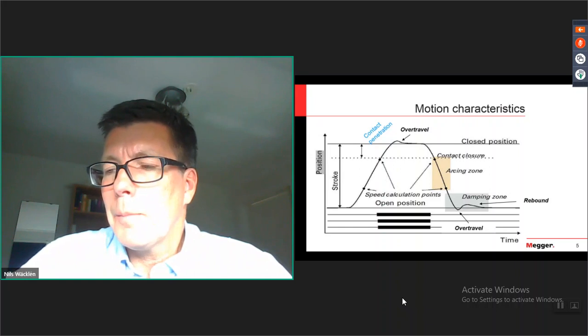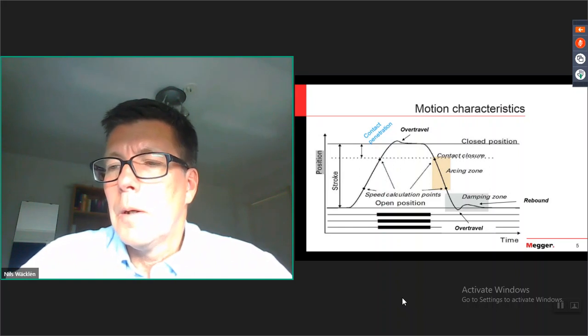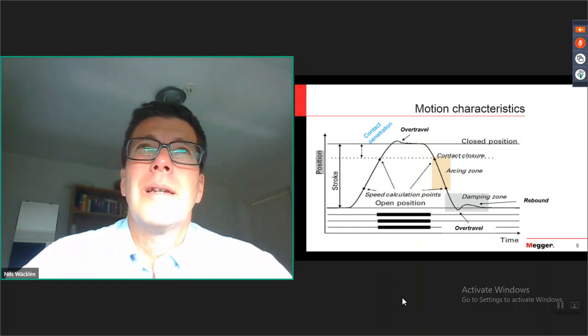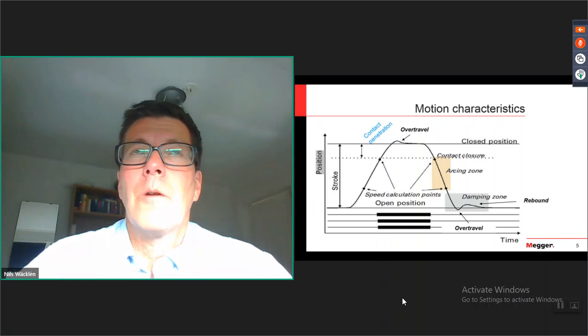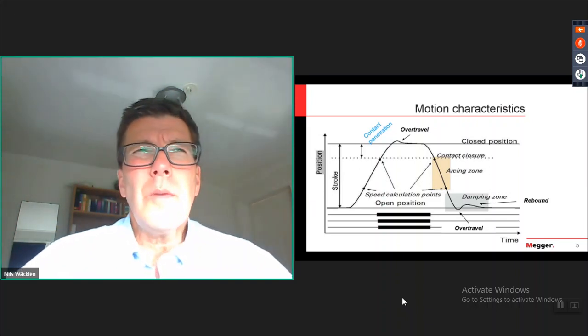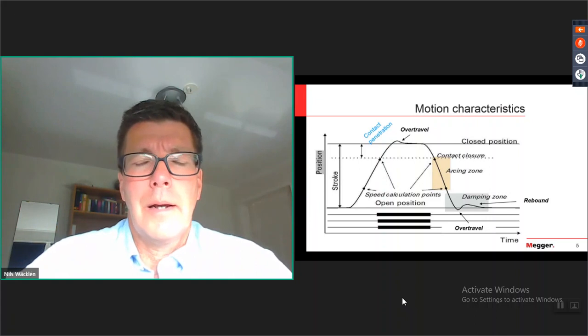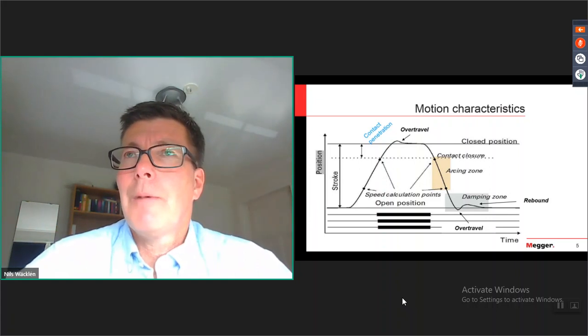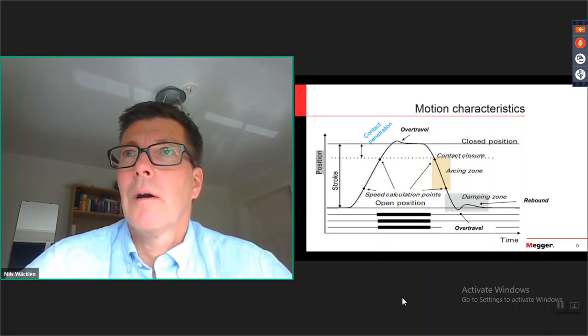The bouncing time depends on the speed and the length of the arcing contact, of course. As an example, if you have a 20 millimeter long arcing contact, and let's say you have a closing speed of 3 meter per second.